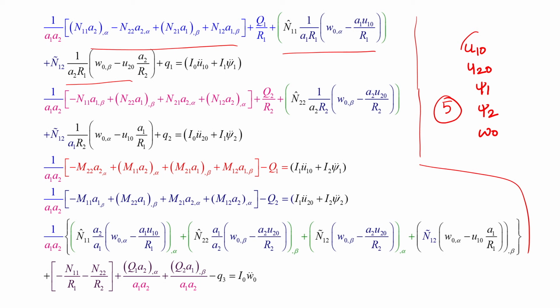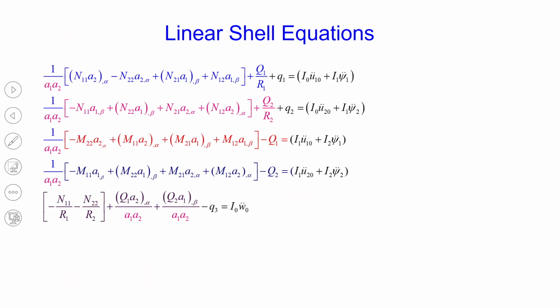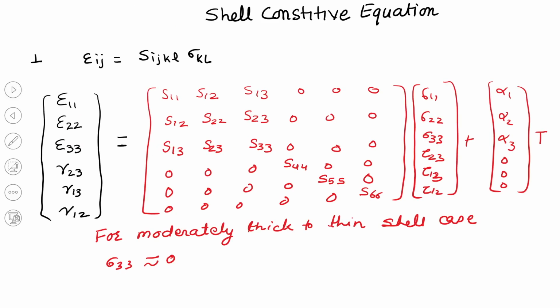We use the shell constitutive relations. I have also given the linear shell equations; in most cases even the linear shell equations are complex and difficult to solve. Containing the nonlinear terms makes it even more difficult. So, from a lecture point of view, our aim is to explain the basic steps of how we solve a linear equation, and then later on nonlinear problems can be solved. For that we need the shell constitutive relations.